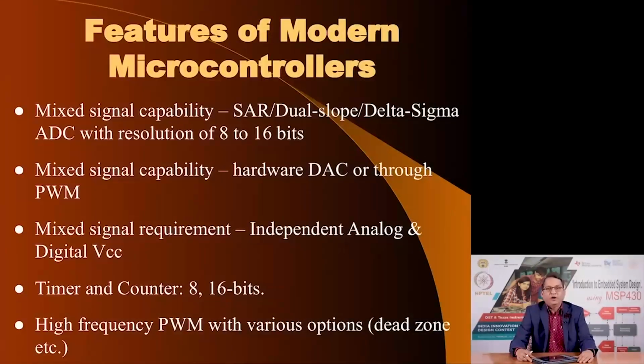Then our modern microcontrollers are great examples of what we call mixed signal circuits. Mixed signal means it is not purely digital, it is not purely analog, but it is primarily a digital circuit with analog capabilities, and therefore it is classified as a mixed signal circuit. For the mixed signal capability, one important feature is that it should have an integrated analog to digital converter.